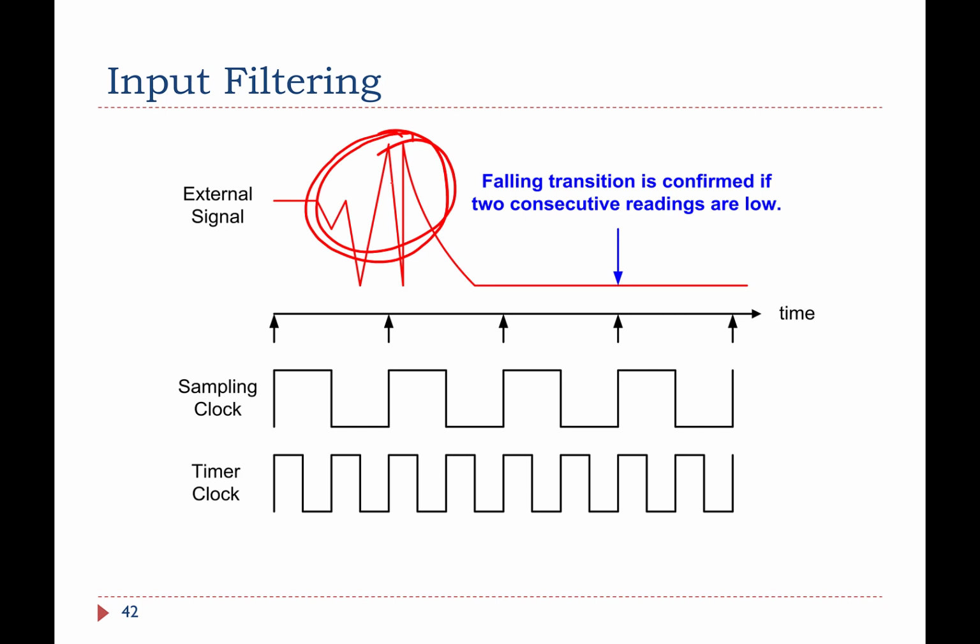And we can do more filtering than just that. We could say 2 or 4 or whatever. But you can clearly see, okay, it's supposed to have gone down there to the minimum, and if everything was perfect and we had no bounce, maybe we'd have something like this for our signal, and then maybe this one would indeed trigger it. But since it's going up and down, that one doesn't count.